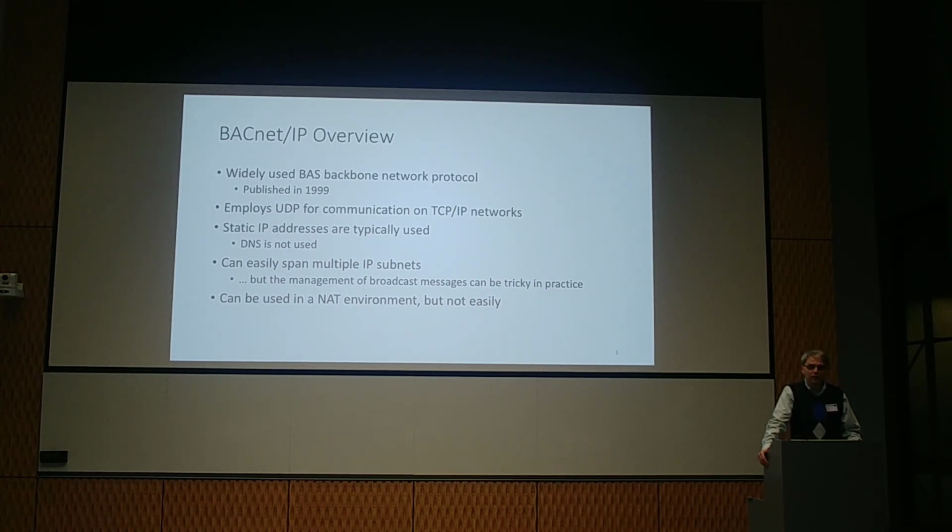Another characteristic of BACnet IP, and more generally BACnet, is that you really want to use static network addresses. BACnet standard does not require that, but systems tend to work a lot better if you use static addresses, and in particular on IP networks that need static IP addresses. This is usually fine, but sometimes when you go to the IT department for a new project and you want 1,000 static IP addresses, they look at you like you're a little bit funny. So certainly one of the things that we were trying to do in BACnet SC is to see if we could relax that requirement a little bit.